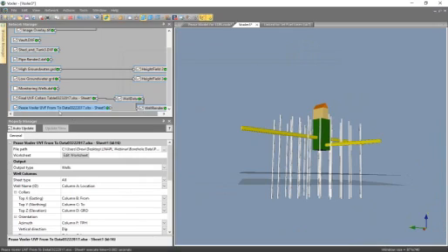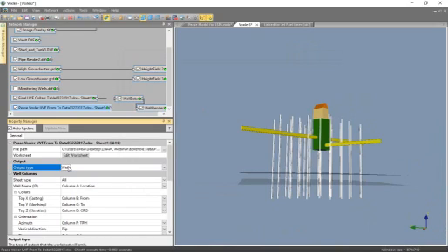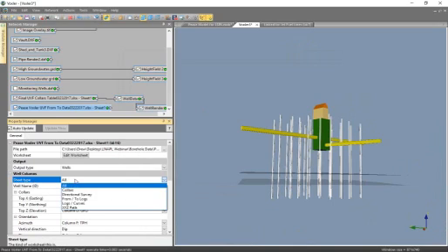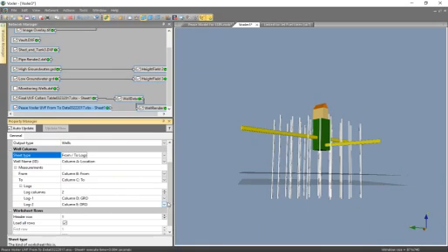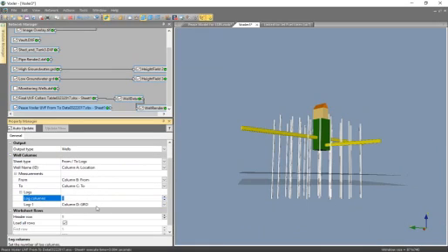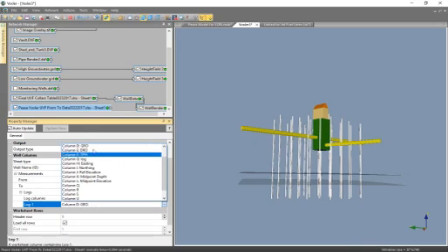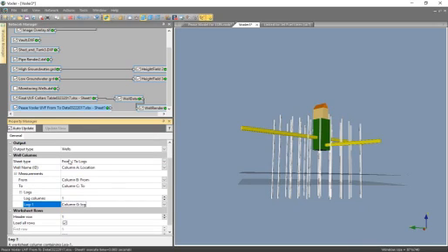And you can see that this has now been added to our network manager. And again, we needed to assign the appropriate columns in the property manager. So I'm going to go ahead and do that right now. Again, the first thing that I always want to make sure is that the output type is set to wells and not points, because this is borehole data or well data. And I'm going to change my sheet type here to From To logs, because we know we're working with From To data. And I'm also going to change my log column down to 1. And I'm actually going to pull the log value here to render along the borings.